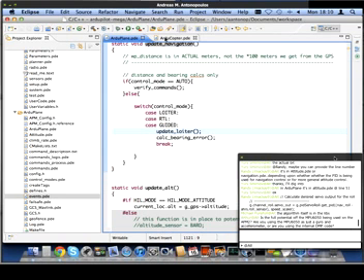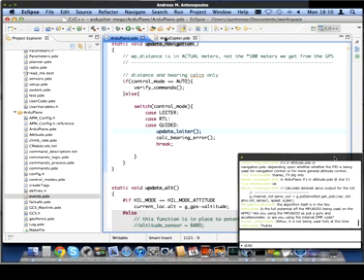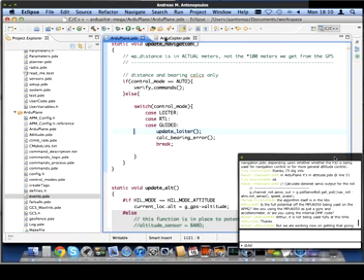Does the ArduPilot use sonar, or is it just for ArduCopter? There is sonar code in ArduPlane, but it's untested. I've never flown with a sonar on my plane. I have flown it on my copter. Doug has experimentally tried automatic landings using sonar on ArduPlane, but while the code is there, it's disabled by default, and it hasn't had enough testing for us to call it mainstream.